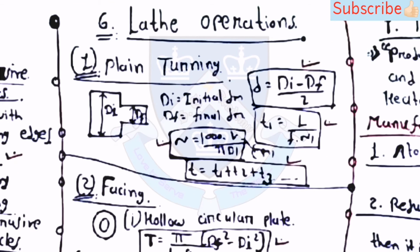Then the sixth one is lathe operations. In that there are 4 to 5 lathe operations. First one is the plane turning operation. D is equal to Di minus Df by 2. Then T1 is equal to L upon F into N1. Then N is equal to 1000 into V upon pi into D1, and T is equal to T1 plus T2